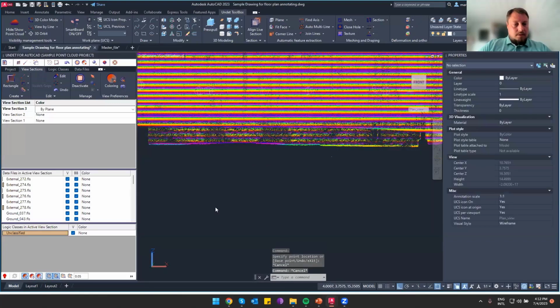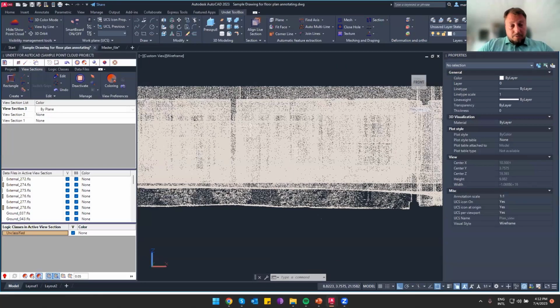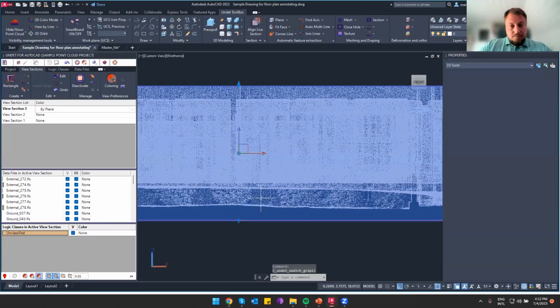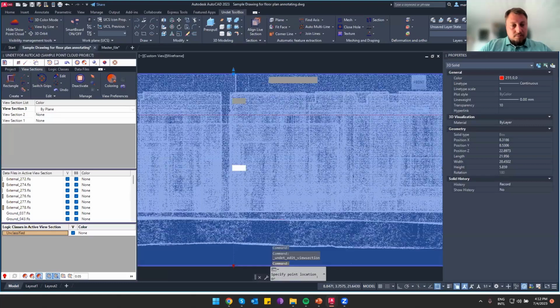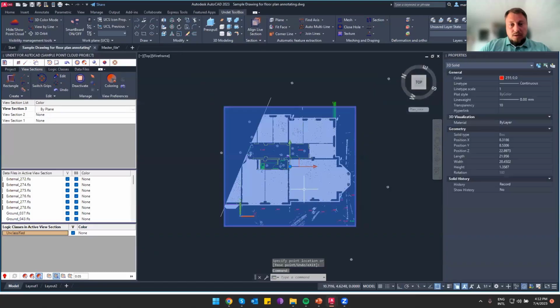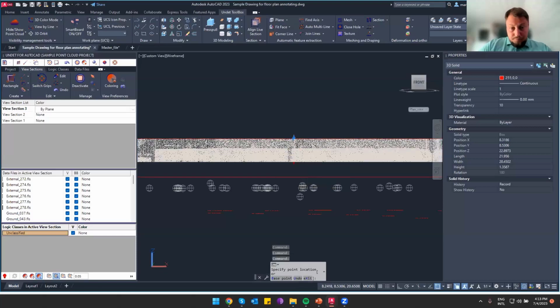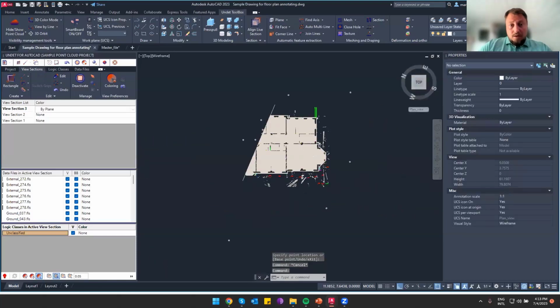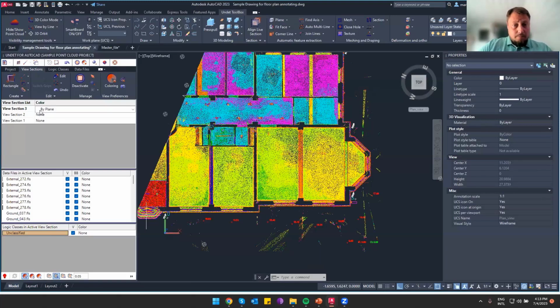So maybe I will switch the coloring mode, because now if I'm using the coloring by plane, each time it's rendering the whole coloring mode. So now I want to see only the ceilings. So I'm just slicing the ceilings. Okay. Not all ceilings I see, so I will increase the slice. Now we see all the ceilings, going to the view, coloring by the section, by plane.